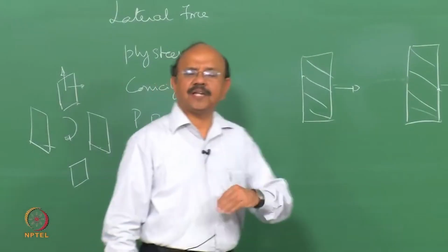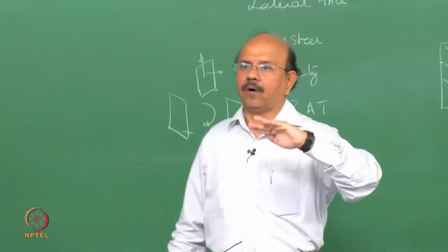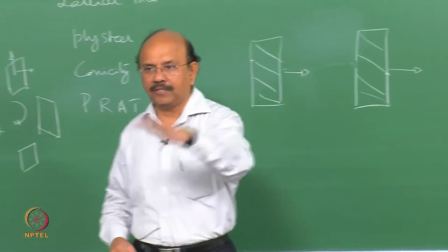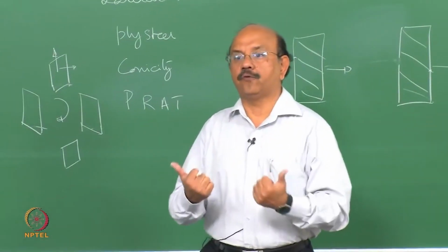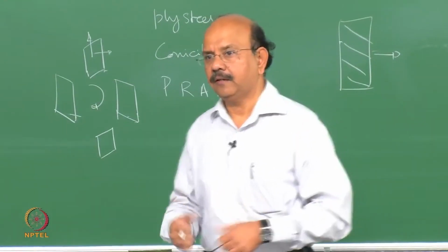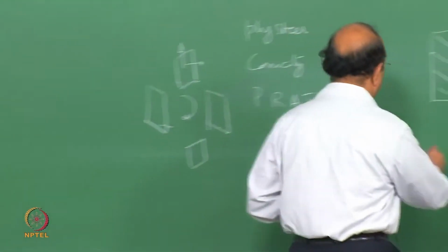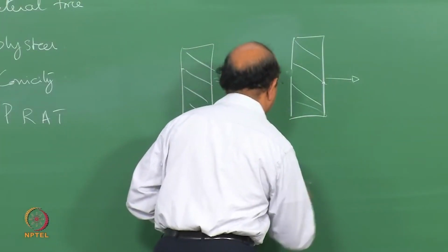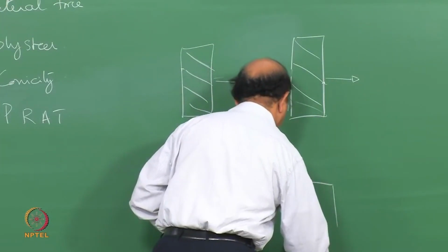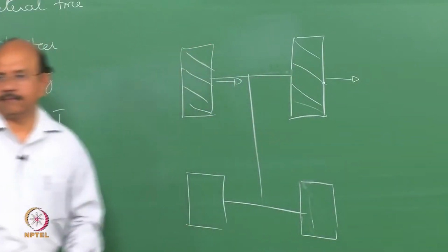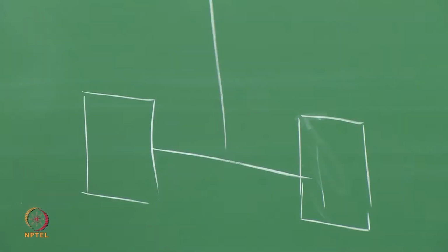So the first thing is that when I roll the tire on the road, remember that ply steer is due to the change in that curvature. So when I roll the tire on the vehicle, automatically a lateral force is generated. So a lateral force is generated in the front and the rear. Let's say that's my rear tire. Let's say that is the vehicle. Now, I have a number of forces that are acting.